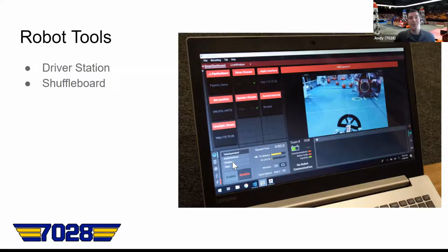A practice would run it like we're running it in an FRC competition. It would start our robot disabled, would give us a countdown of a few seconds, then it would run autonomous for 15 seconds and then switch into teleop, and it would run our timer out until our game is over, 2.5 minutes, 3 minutes, whatever it is, and then the robot would become disabled automatically.